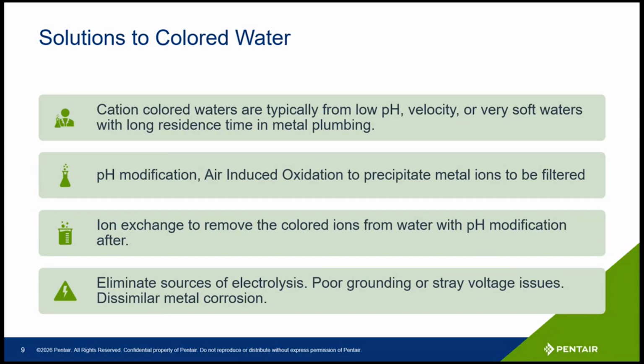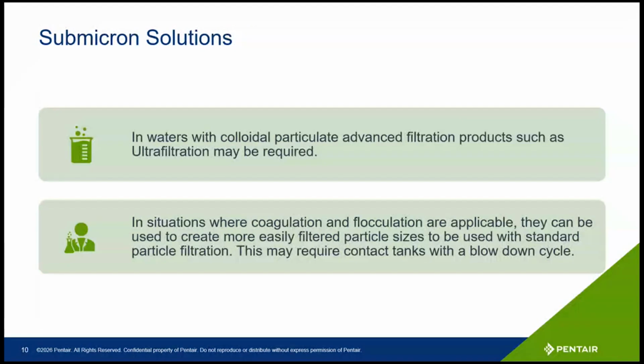And in situations where it may be warm enough that you can do coagulation and flocculation in a storage tank, in an atmospheric situation, sometimes with colloidal issues, that may be the best choice, and then follow that up with a bulk backwashing sand or aluminum silicate sort of fine filtration media down to 3 micron to remove that coagulated and flocked material.